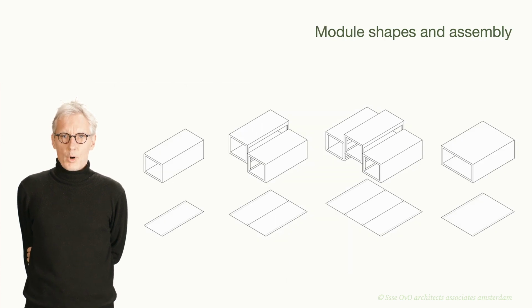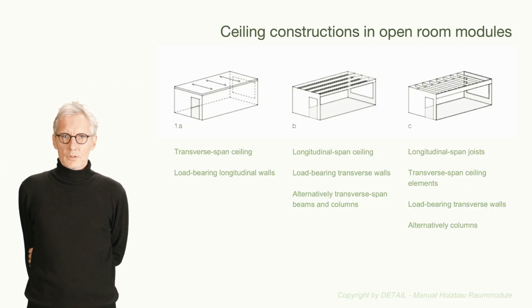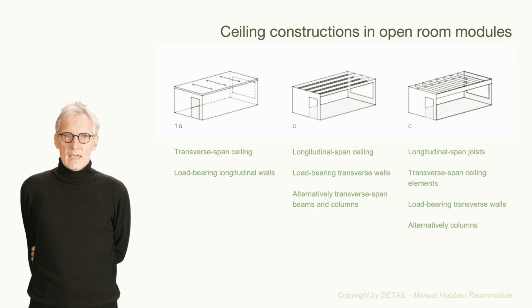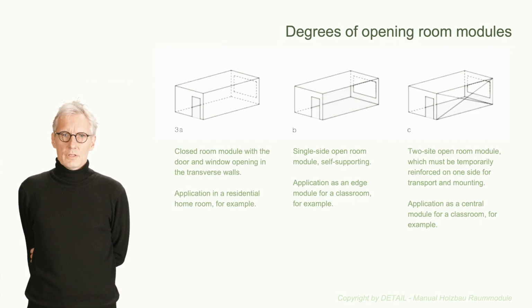From a design standpoint, you have modules that can vary in shape, size, and function, opening doors to creative and efficient use of space. What does a module consist of? As a rule, room modules are mostly cuboids, with rectangular floor plans and 6 boundary surfaces, of which 2 each have the same size. In constructional terms, one distinguishes between longitudinal walls, transverse walls, the ceiling, roof, and the floor.